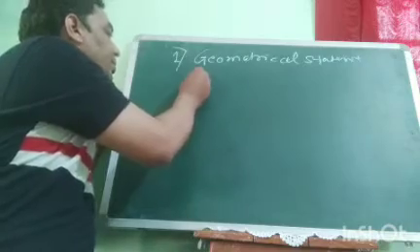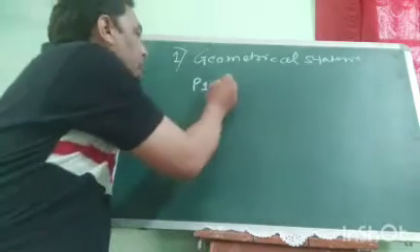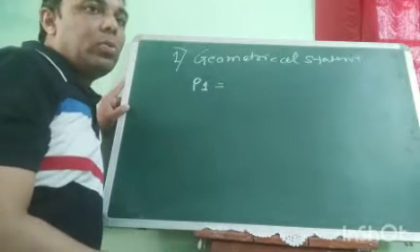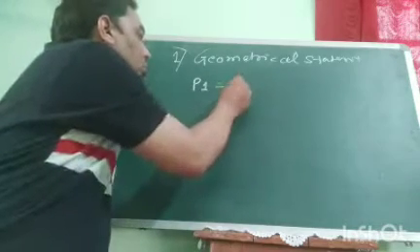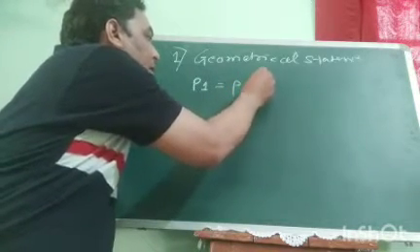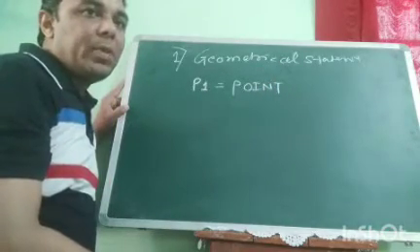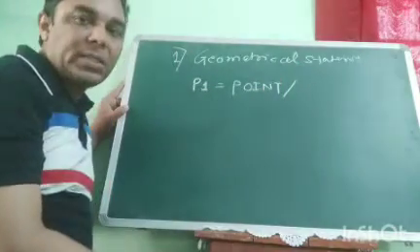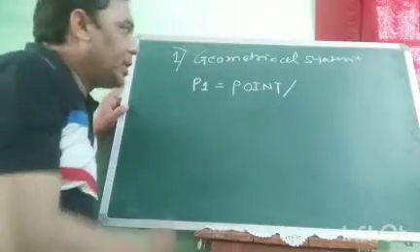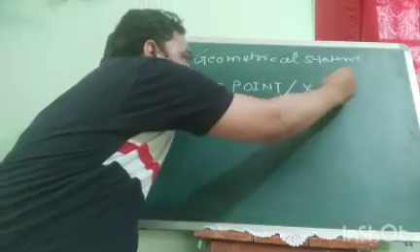So first we'll start with what we saw in the last lecture: if I want to give the point indication, the point symbol, I consider point P1, and for that point P1 I can give the syntax coding in APT part programming as follows: POINT. We just need to write it in simple English terms, and the point location in the form of coordinates like x, y, and z coordinate. So we need to write the x coordinate, then comma, y coordinate, and comma, z coordinate.